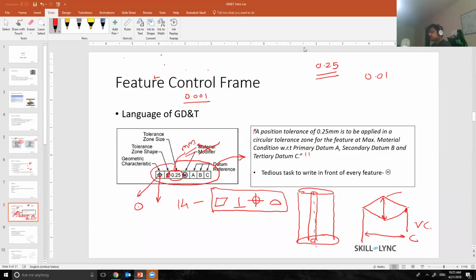So it's mostly based on your communication with the supplier, and there is no specific standard, ASME, that says, okay, the flatness should always be 0.25. It's more about the carryover part. So if the previous part has 0.25 tolerances, it's going to work in the same way for the new part. And in the next slides, I have example tolerances for machining position, machining flatness, and we'll talk about it.